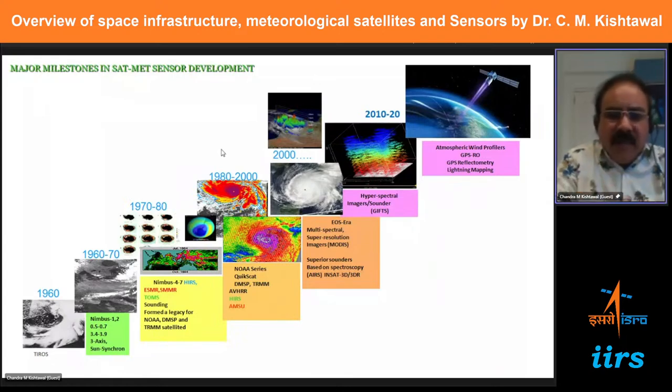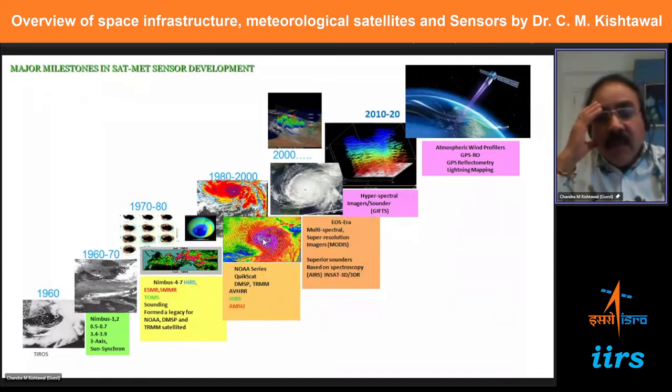of microwave sensors. And after that, you can see this picture shows the surface winds, and this is one of the very valuable observations coming from microwave satellites. They can give you the winds over the ocean surface, not the ground surface, because when wind blows over the ocean, it creates waves and roughness in the sea, and this roughness is directly proportional to the winds blowing over the ocean. This roughness changes the emissivity. So from this roughness, they can get an idea of the wind speed, and it is fairly accurate. Actually, it is accurate to less than 2 meters per second. So it's quite good accuracy from a satellite platform.